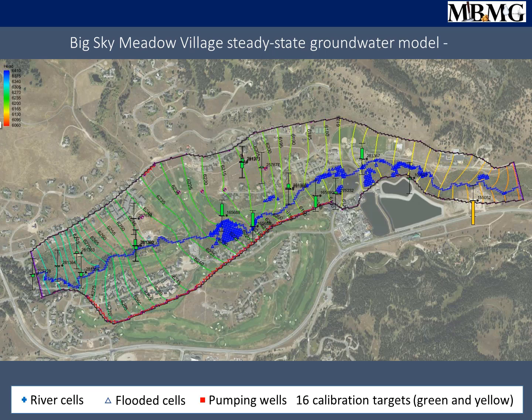So then we used this program called automated parameter estimation, a computer program that works with MODFLOW and other programs. And we just said, well, let's range it between 50 and 200 feet per day and just let the program optimize the solution. So that's how we got this really nice calibration. And the next slide will show the parameter estimation results.